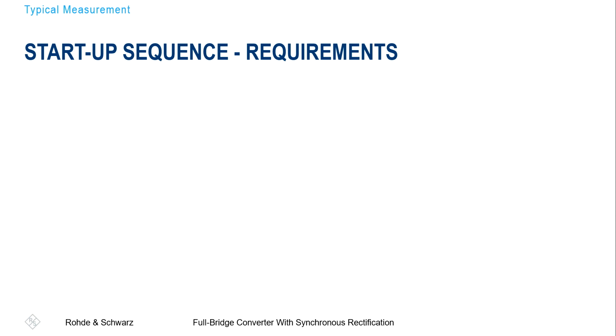You need to repeat and double check that the switching pattern, including all delays and oscillations, is correct, or that's what you want to see. The next thing we will have is the startup phase. I mentioned that already with this auxiliary supply. And this is one of the most complex